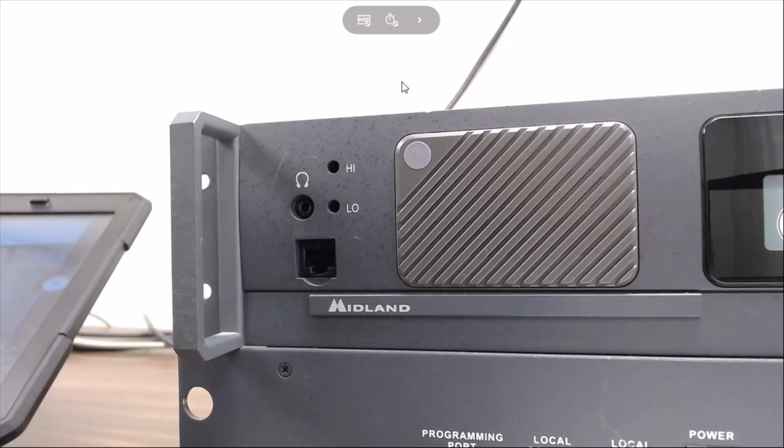Okay, I want to go over some of the adjustment spots in the radio and how to get into the internal front panel menu. To start off with, I wanted to look at the power. This is your high power adjustment. There's a pot inside there, and this is your low power adjustment. It's about an inch or two inside there, so you kind of need a little bit of a longer tool, but it's just a standard pot, and it's fairly easy to adjust. It's a bigger pot compared to the other ones. So that's the power out.